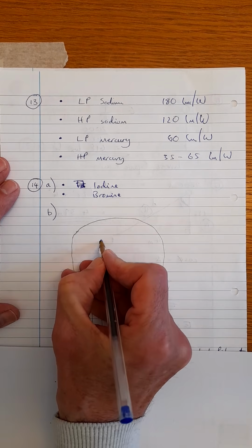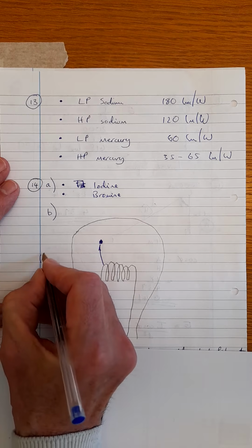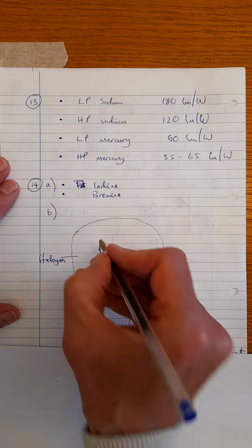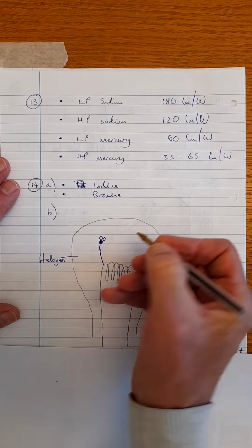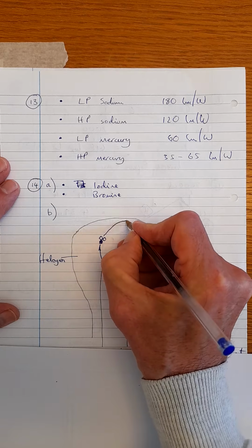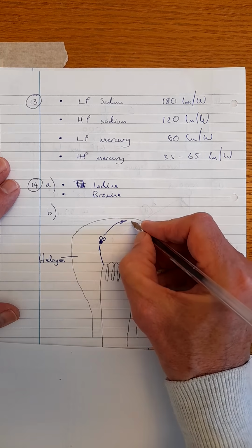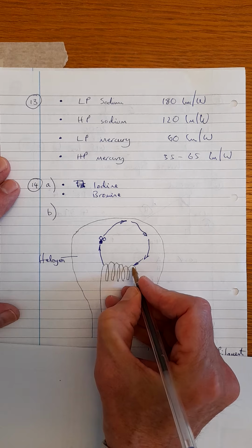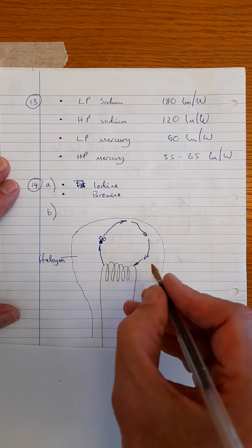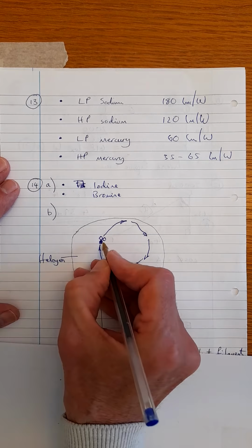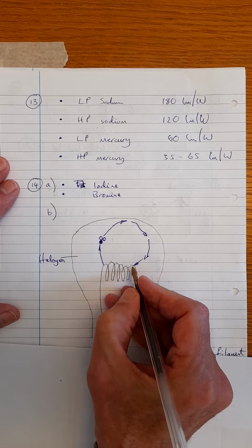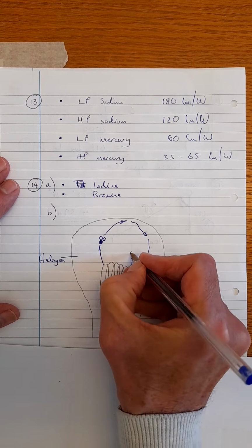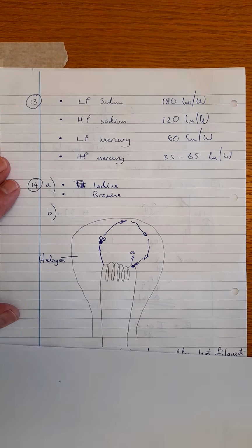But what happens? So it leaves and it will meet the halogen. Let's write halogen. So there is halogen inside the glass envelope. So it will meet it and it will form a new molecule. That molecule will travel around. It will not stick to the glass, and it will travel around until it comes back somewhere and it lands back on the filament. At that point, these two particles, the tungsten and the halogen, will reverse. The tungsten will now stay on the filament and the halogen goes back into the atmosphere of the glass envelope.